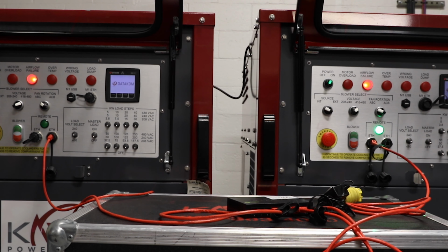Let's pick up where we left off. You have created a group and added load banks to it already. As you can see, our group consists of one 1000 kW load bank and one 600 kW load bank, giving us a total capacity for our group of 1600 kW. But if you recall, we are going to be testing a 1500 kW generator, so we set up the group to give us a maximum of 1500 kW, including fan power.